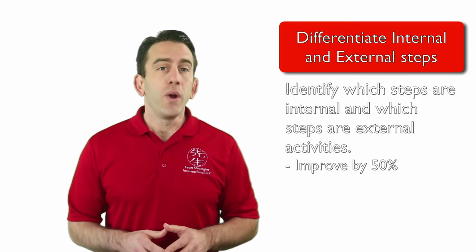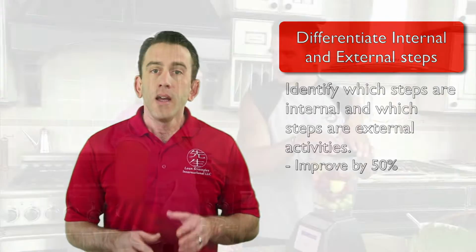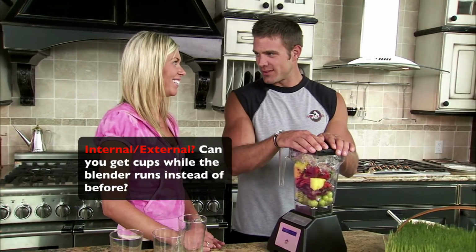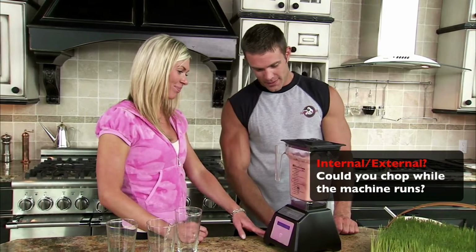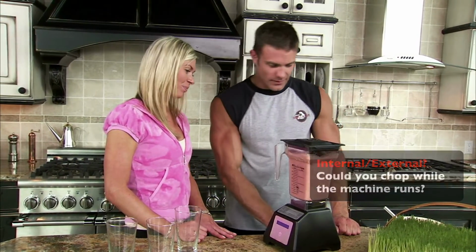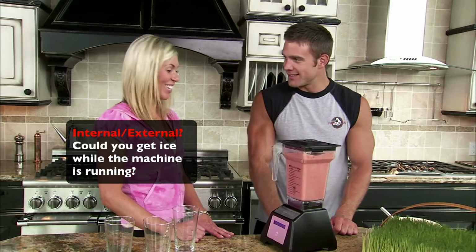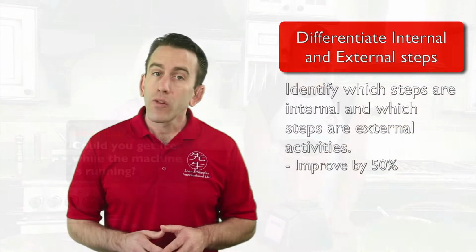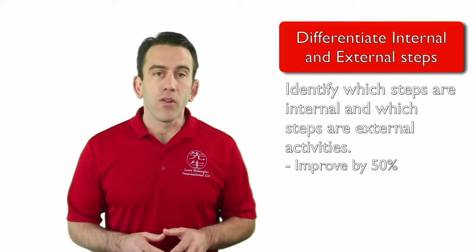After this, we differentiate internal and external steps. This is one of the most important steps in the reduce methodology. When you differentiate and distinguish steps that are internal and external, it becomes clear that activities like preparation and transportation of items are better done while the machine is running.